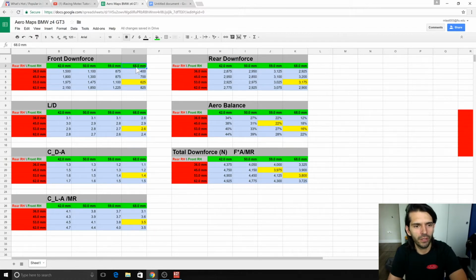So the front is at 68 instead of 70, so it goes down about 2 millimeters on the average, and the rear goes down about 8 millimeters on the average, which again demonstrates it's a function of obviously the spring rate and also the aerodynamic load as to how far the rear of the car squats down. So that's the reason that these values are like that.